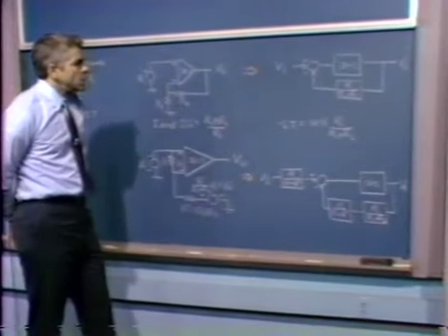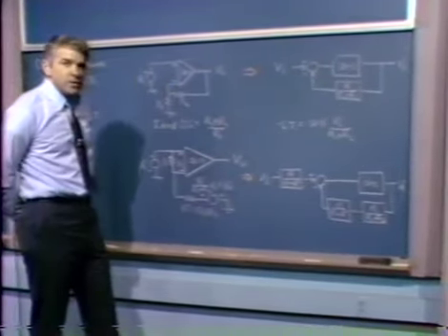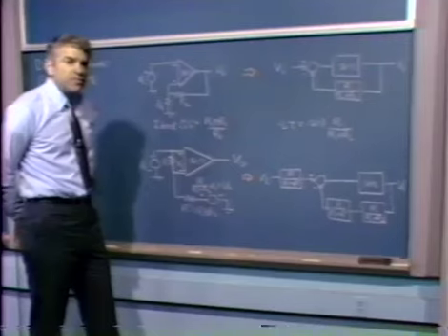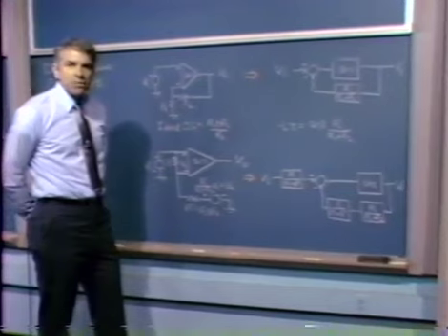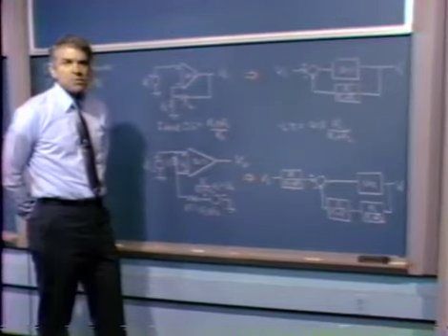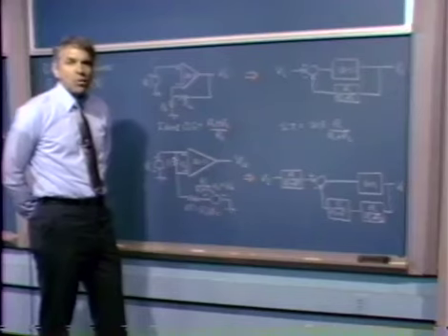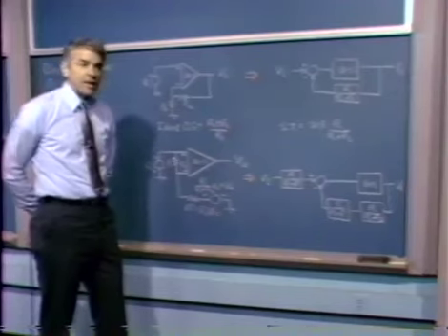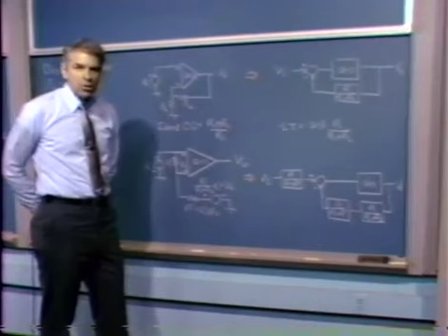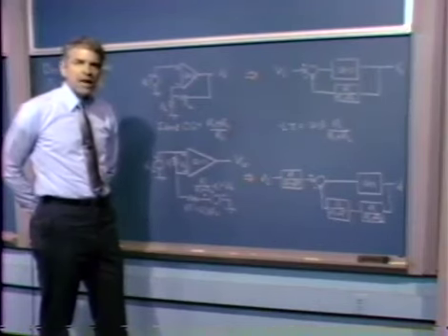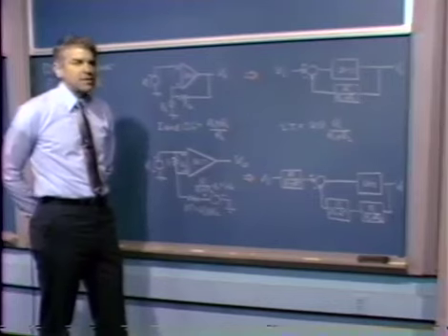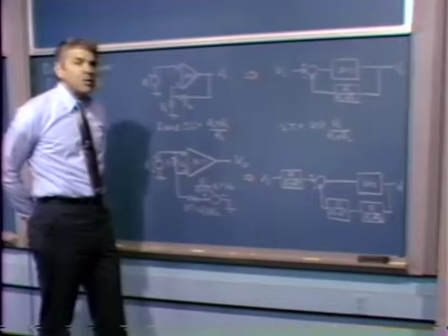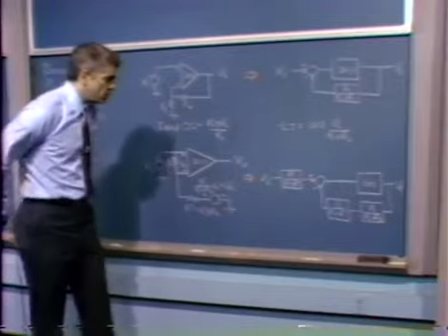Now, suppose we build one of these, and we find that the system is not acceptably stable. We suspect that the loop transmission magnitude is too large: either the system is absolutely unstable, or we have too large an MP, or the damping ratio of the dominant pole pair is too small, or somehow we've gotten an indication that the system is not acceptably stable. How can we lower the loop transmission magnitude?